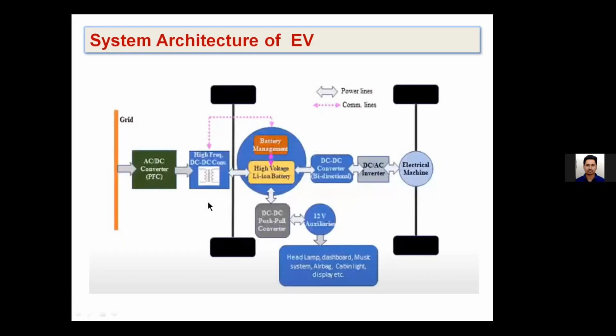So from this slide, it's very clear that there is a definite requirement of power electronics here. From the battery to the motor, in between, we require some power electronic conversion. And one more thing is, it should be bidirectional in nature. We have discussed different modes of operation of the OBC, or onboard charger. There we have discussed grid to vehicle, vehicle to vehicle, different modes. Sometimes a part of the energy may be fed in this direction during regenerative braking and all. That's why this particular converter should be bidirectional in nature. That also needs to be taken into account.